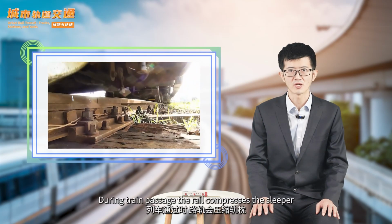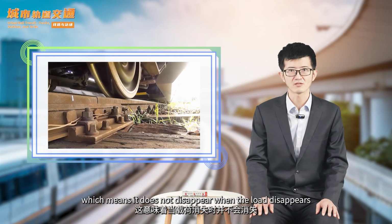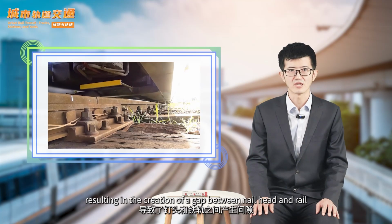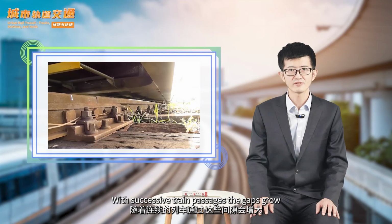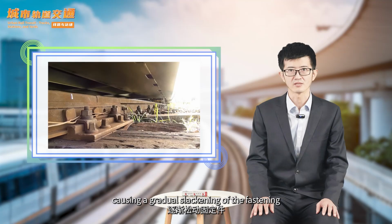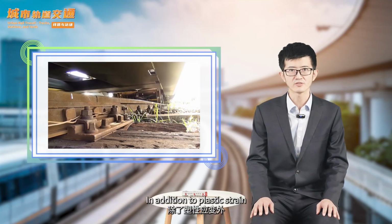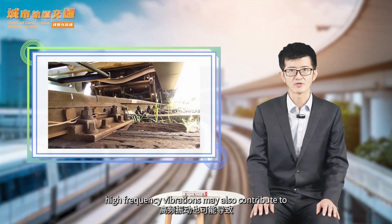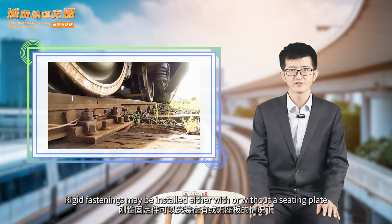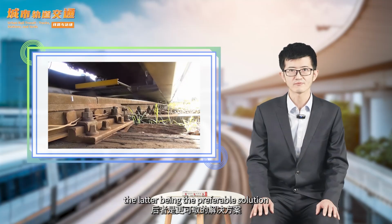During train passage, the rail compresses the sleeper, and part of the strain is plastic, which means it does not disappear when the load disappears, resulting in the creation of a gap between the nail head and the rail. With successive train passages, the gaps grow, causing a gradual slackening of the fastening, which affects safety and may be the origin of a derailment. In addition to the plastic strain, high-frequency vibration may also contribute to the widening of the gaps and the slackening of the fastening. Rigid fastenings may be installed either with or without a sealing plate, the latter being the preferable solution.